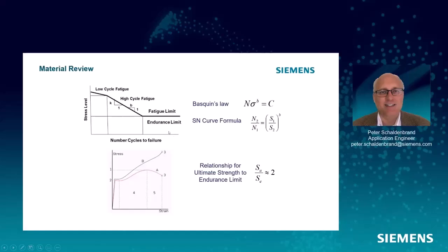Now I have worked with clients that have had vibrations that were down here and they want to develop an accelerated test. This was something on a manufacturing floor and it was a PCB. In that case, we could accelerate by a lot. So it really depends how much you can accelerate by, where you are on the curve. But if you take a proving ground schedule, I guarantee you're going to be in this high cycle fatigue.